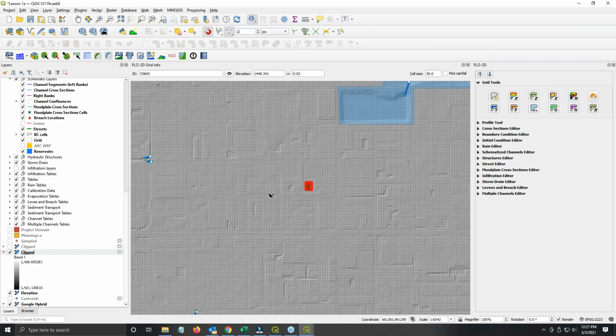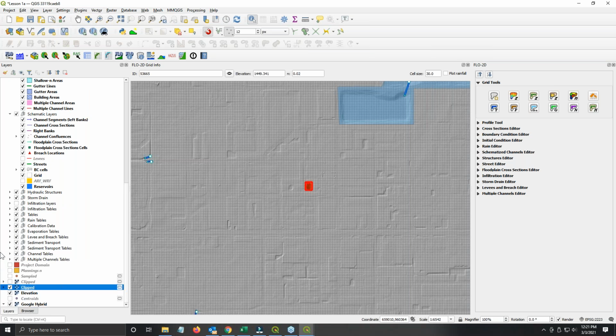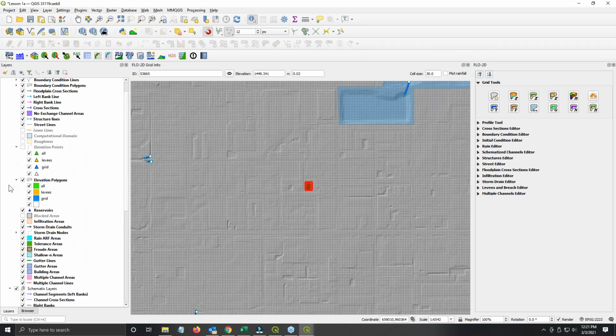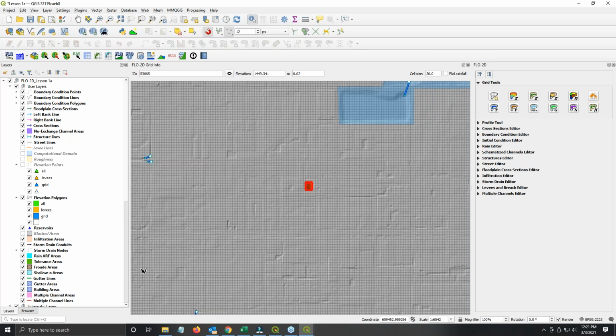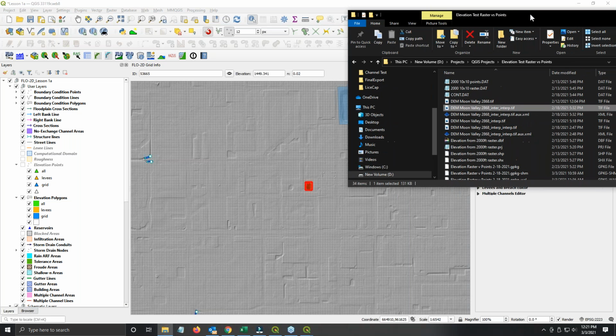And then I could just import that as a shapefile vector layer. But if you can't open your project in Mapper because it's too big or something like that, you can take a point layer and you can rasterize it. And it's not even difficult. So it kind of goes along with this topic. So we'll just go ahead and add it today.